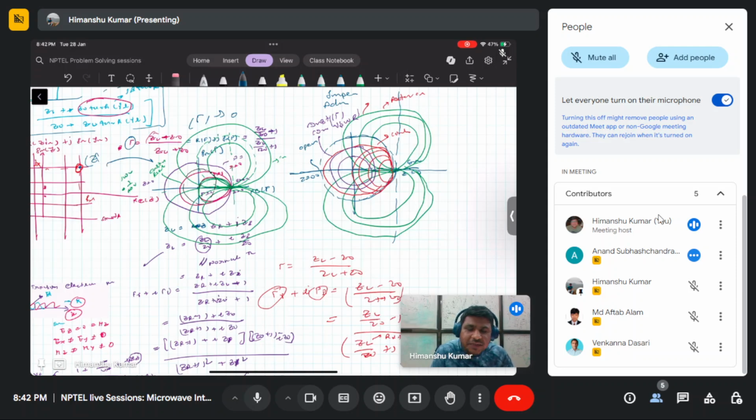The Smith chart was developed by analyzing the reflection coefficient equation. The idea is that all the coaxial lines are 50 ohm lines, so any load you can represent in terms of the complex reflection coefficient you can calculate. So you can do back and forth conversion.